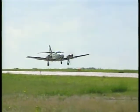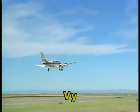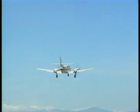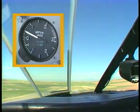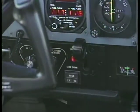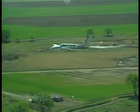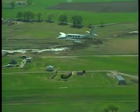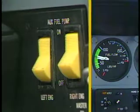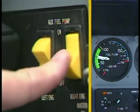After liftoff, accelerate to the best rate of climb airspeed, or VY, and maintain that speed for the initial part of the climb. Retract the landing gear when you have a positive rate of climb and can no longer land on the remaining runway. If flaps are used, bring them up in accordance with the pilot's operating handbook. Once you've reached a safe maneuvering altitude, reduce power to the desired climb setting. Turn off the electrical fuel pumps one at a time while monitoring the respective engine instruments.